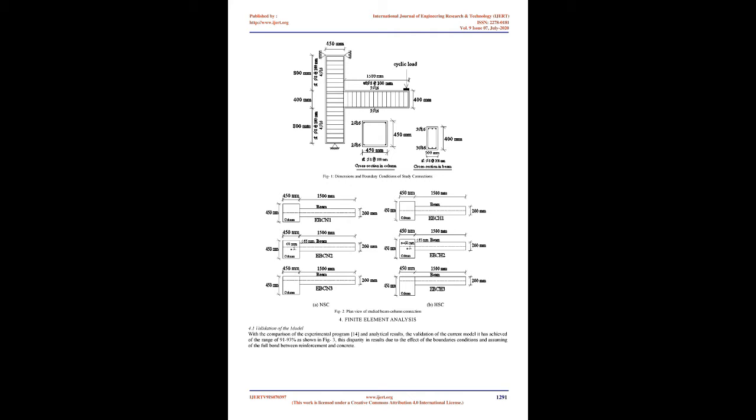The investigation's main objective is to research the seismic behavior of both NSC and HSC eccentric exterior beam column connections and draw an analogy between both types of connections. The finite element method is utilized via the software ANSYS to expand this analysis. The applicability of the provisions on joint shear force used by international codes, e.g., the American Concrete Institute, the New Zealand Code and the Eurocode 2, are investigated when applying to HSC eccentric beam column connections.